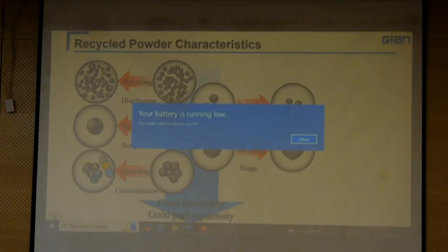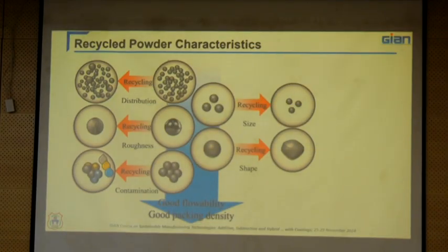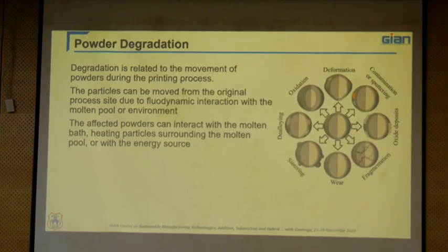Okay. And powder degradation also takes place. You cannot store the powder particles like that, because if you keep powder particles for 5 years and again use the same powder for additive manufacturing, what will be the problem? Can you use that kind of stored powder? Yes, for ferrous based materials. For non-ferrous materials, we cannot store them like that, because they will contaminate, they will oxidize, impurities or foreign particles may contaminate them, and even during transportation it may be contaminated.